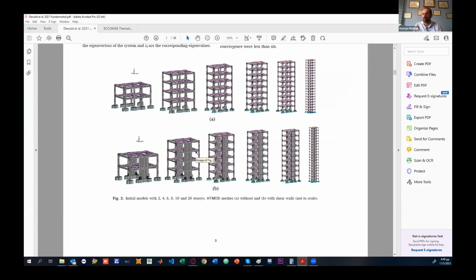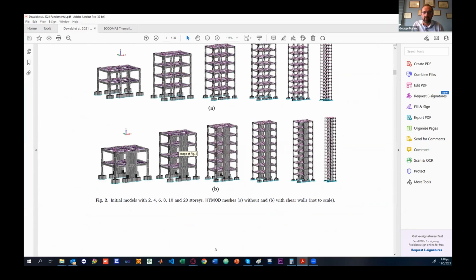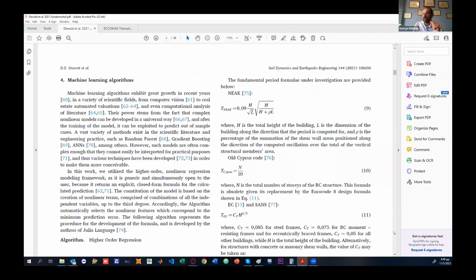As you can see in this case, the beams and columns, part of them are modeled through the beam column flexibility based element, and the rest of the structure is discretized through hexahedral elements and embedded rebars, that can take into consideration yielding, rupture, and of course the concrete can take into consideration crack opening and closing of cracks, micro cracking, and so on.